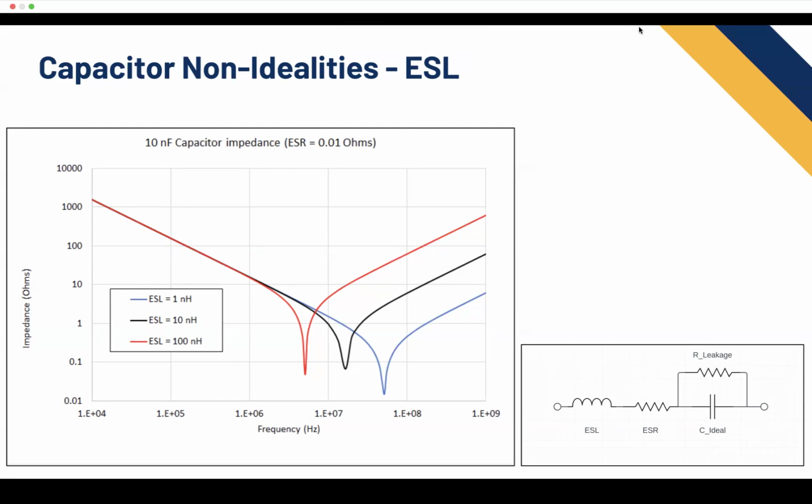Like I was saying, you asked what size capacitor do we put, and how do we determine that? In order to explain that, I've come back to our equivalent series inductance slide because I wanted to use this same graph here. This graph shows if you change the equivalent series inductance, but the same thing happens with the resonant point if you change the capacitance, right? Because that point, 1 over the square root of LC, is where you have the lowest impedance.